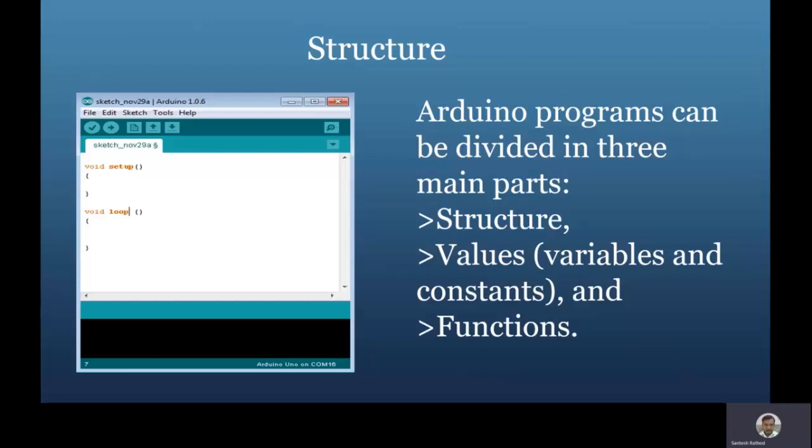The next main function is the loop. After creating a setup function which initializes and sets the initial values, the loop function does precisely what its name suggests: it loops consecutively. Suppose you are working on a project, for example the blinking of an LED, wherein you want the LED to blink after a particular interval of time or seconds, then you can put that into the loop. So it allows your program to change and respond. It is used to actively control the Arduino board.